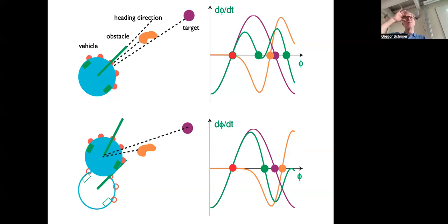So this time scale of relaxation, right, how quickly we go to the attractor, is sort of a design variable. A priori, this is just a mathematical conception, so we could just make it very fast. So we're always not close to an attractor. In practice, when you implement that, it's actually a question of computation time, and that has to do with sensory updating. So when you do this on an actual robot, you solve the equation numerically, and you use a certain step size in time how to solve the numerical equation. That is not usually a problem for your computer on the robot.